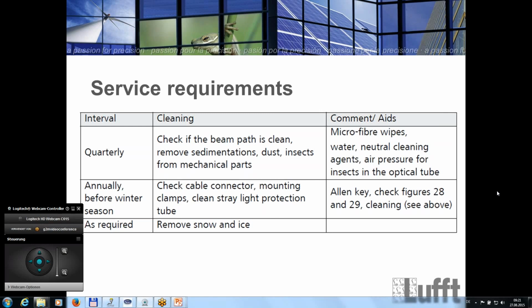So you should, in this case, take a careful look, switch off the laser, maybe to be able to look inside the sensor with an LED or with a flash lamp or whatever to check if it is all right, and if there is some spider nest or whatever before the laser optics, you must remove and clean it.